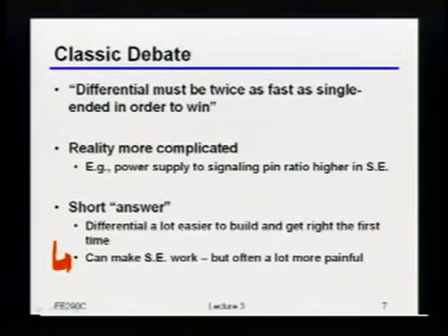And I'll explain why I say that in maybe a couple more slides here. Okay? But that's purely from the signaling standpoint. So it's probably actually the case that, if I really could get it right, single-ended may turn out to be more efficient, just because I have less stuff inside of there. The problem is only, how hard do I have to work to actually get it to work the right way? And so maybe by the time I've done that, I've probably spent the same or more power as I would have in the differential signal. So it's a good question.